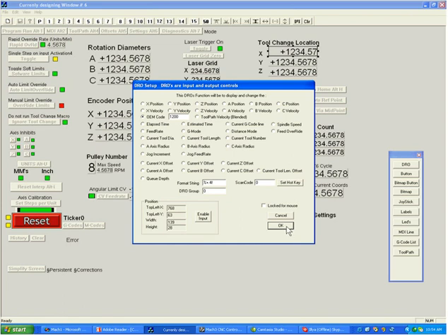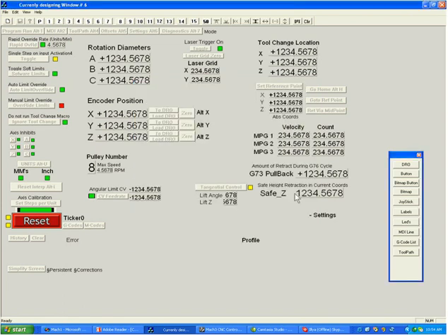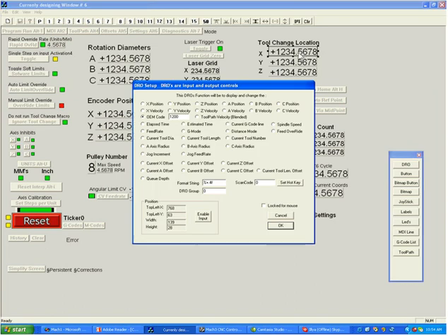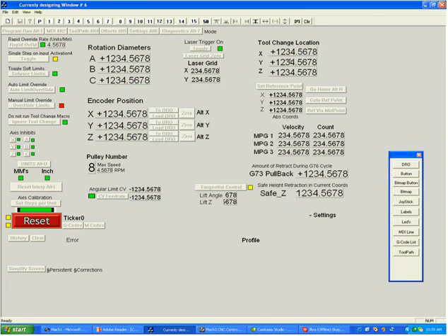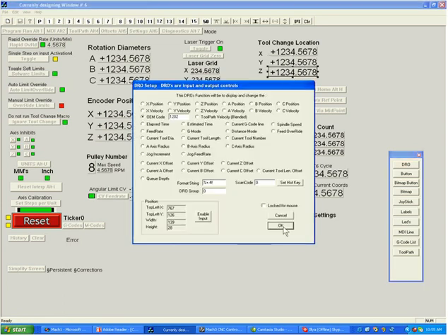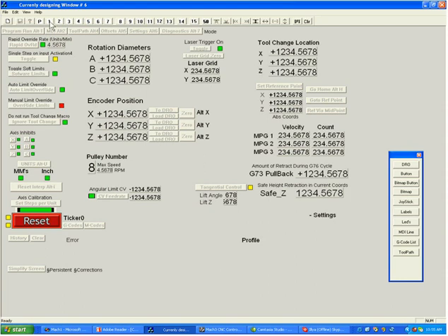In CNC, you normally would want 4 places of resolution after your decimal point. I should note that the program really doesn't care how you display it. It will always use up to 12 to 15 decimal points for accuracy. But these are display issues, and most people want that warm and fuzzy feeling they get from seeing the full 4 decimal places after the point in any number. So, let's say we want to use these tool change locations in our M6 tool change macro. We can see that the X is OEM code 1200, the Y is OEM code 1201, and the Z is OEM code 1202. Let's remember that for the moment.